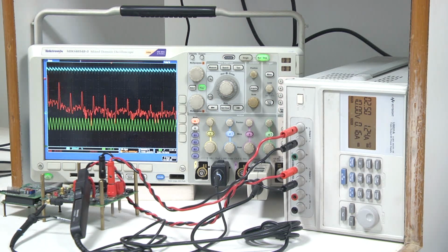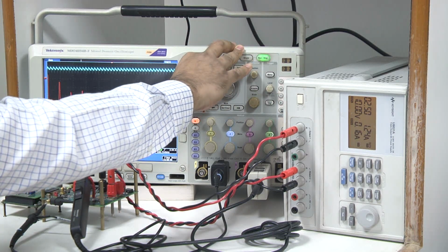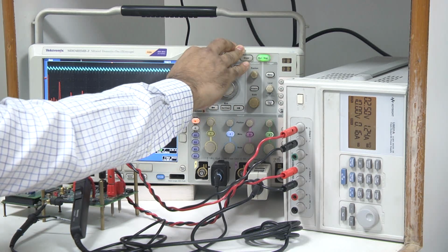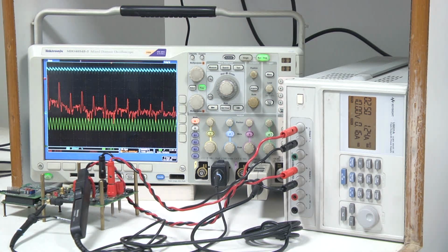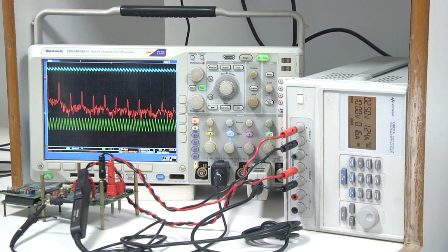So that means it's 200 kilohertz. So maybe this may be the reason that we have not set it properly. That means this offset is slightly shifted, otherwise this is designed at 250 kilohertz. So we saw that in case of constant off time, the ripple is more or less constant if the output voltage is maintained, even though you vary the input voltage, but the switching frequency varies because with higher input voltage the switching frequency is increasing, which was the opposite for constant on time.